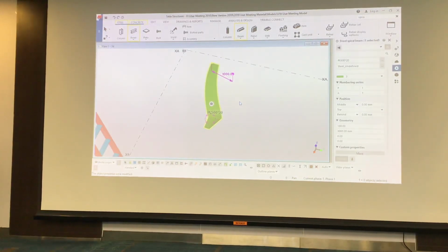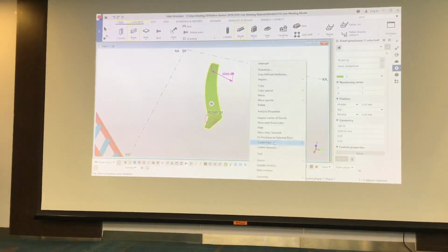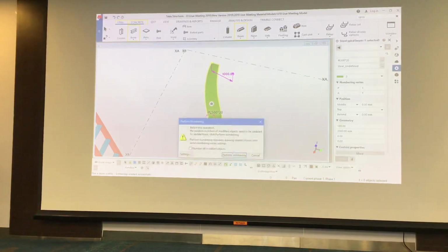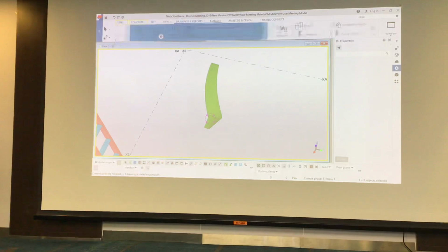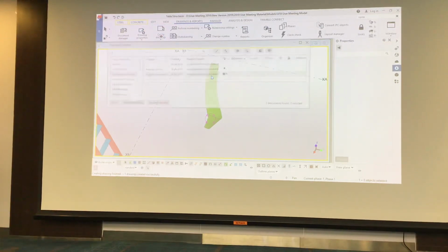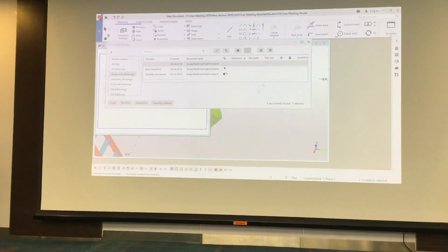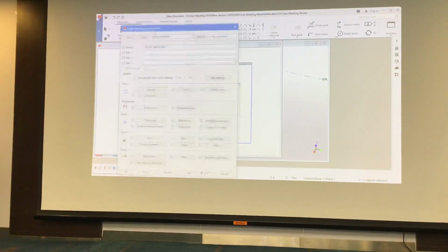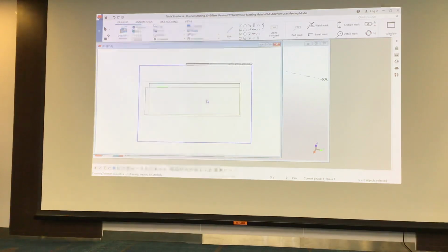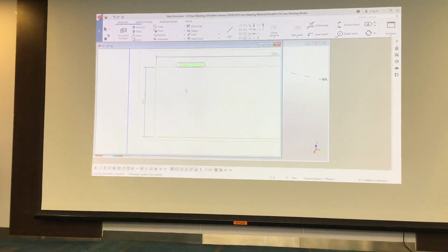Again, if you create a drawing of that, you can say unfold that. Let me do it. So click on this piece here and say give me a single part drawing of that. Go to the drawings, document manager, to do a single part drawing. Hopefully it's this one here. And then again on this one here, you can click on that and say, okay, well, it's plate unfolded. There it is. Look, it's unfolded out. So that is the correct unfolding of that piece.